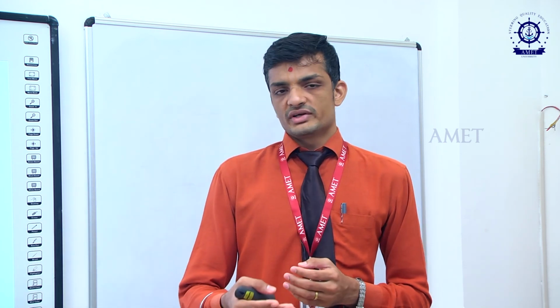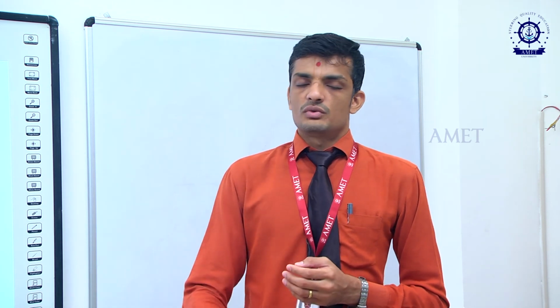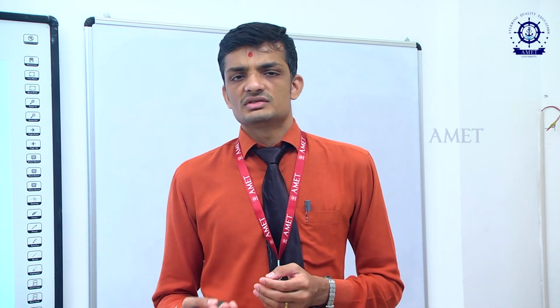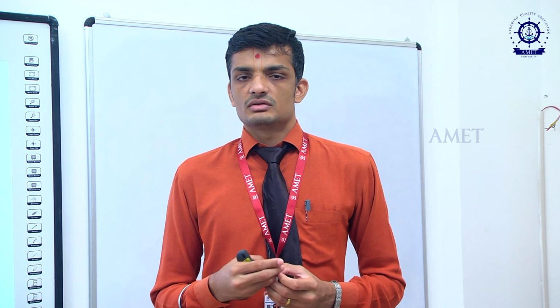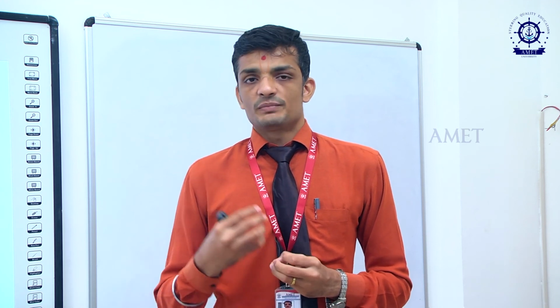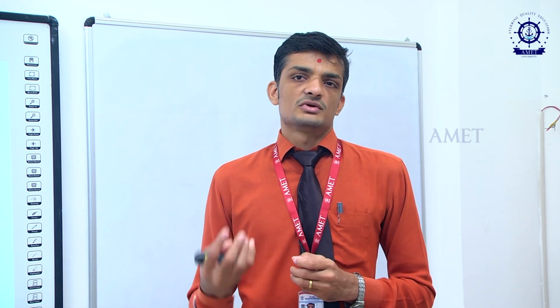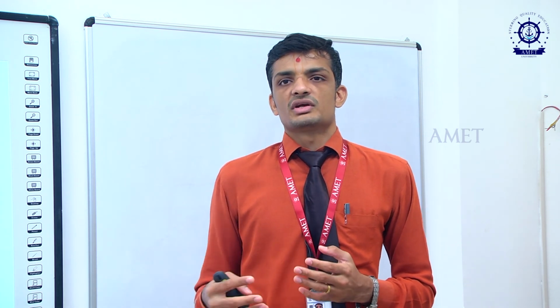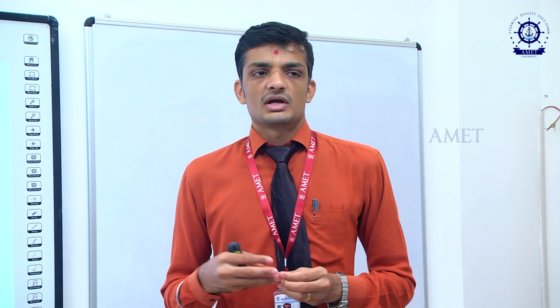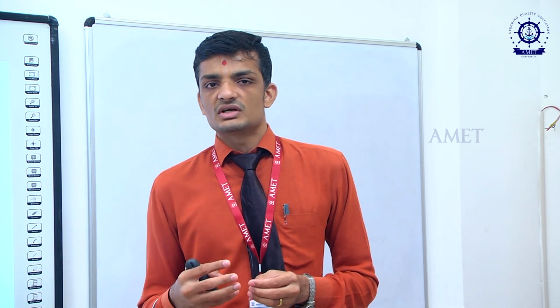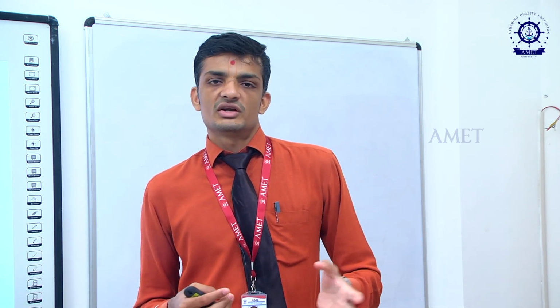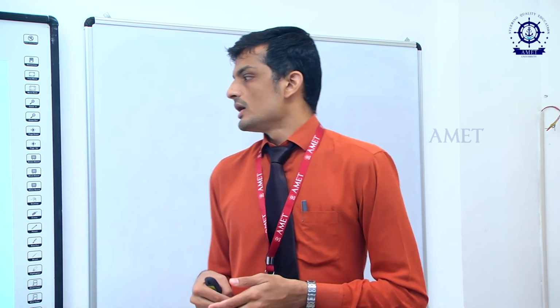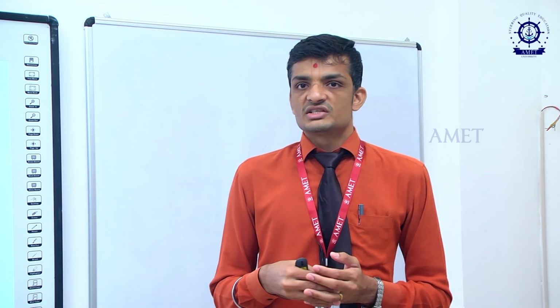So once you have your load vector, you got to import your boundary conditions. Boundary conditions, again, are nothing but what sort of support you are using, at which part a particular response is not available, and based on clubbing together you form your boundary conditions. For example, a cantilever beam, one end is fixed, the other end is free, so the fixed end will not have any displacement there.